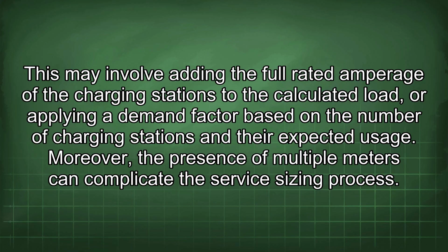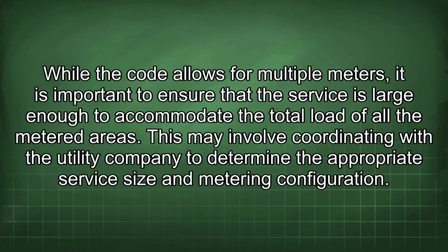Moreover, the presence of multiple meters can complicate the service sizing process. While the code allows for multiple meters, it is important to ensure that the service is large enough to accommodate the total load of all the metered areas. This may involve coordinating with the utility company to determine the appropriate service size and metering configuration.